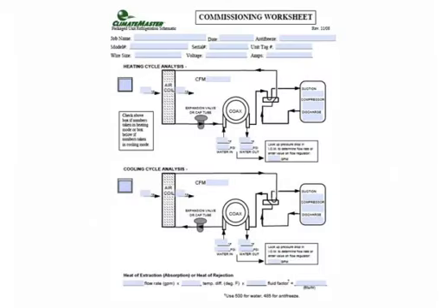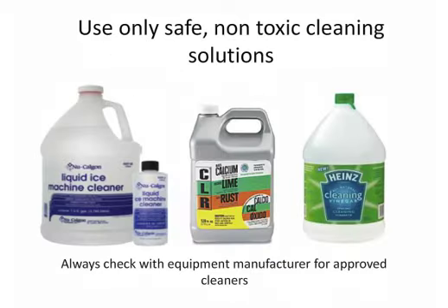Here's an example of our commissioning worksheet. You can see in the heating or cooling cycle, you check the box, you fill out all those flow rates and CFM and things of that nature. Again, date it, model number, job name, all of that, and put it in your project file. If you have the ability, and most homeowners do nowadays, to make a copy and keep it on site with the heat pump, that's not a bad thing to do either.